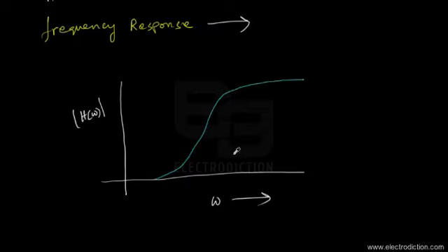Okay, or rather, let's just modify it a little bit. Okay, so that's better. So here, as you can see, we have this sort of response curve for a high pass filter. Now you can see that as the frequency goes on increasing, it reaches a certain point. We would just call it the lower cutoff frequency, and that is characterized by omega 0 over here.